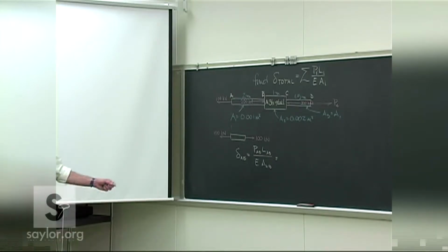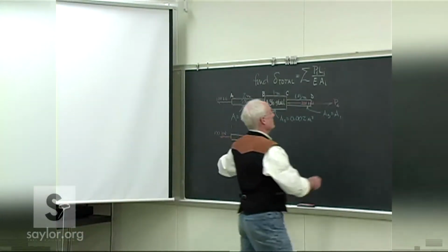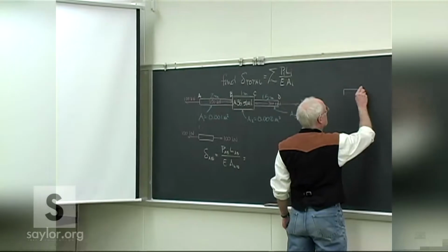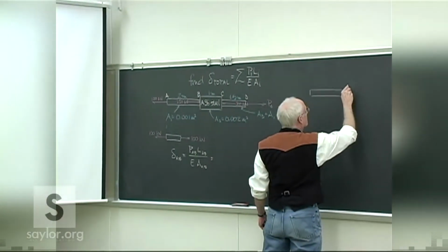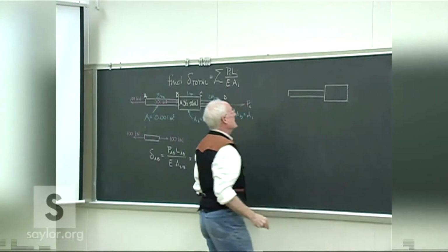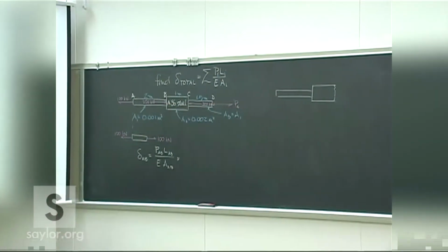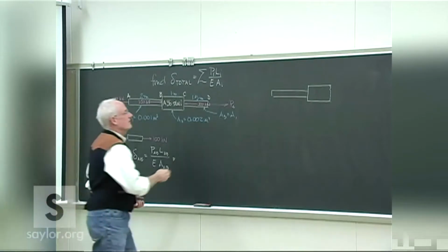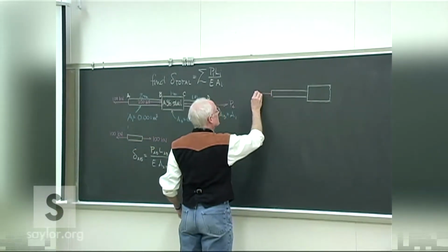Okay, so you can do that real quick. It's again just putting in the numbers, then go to the next section. Put an imaginary cut somewhere down through the piece between B and C, and then again figure out what that internal load is.